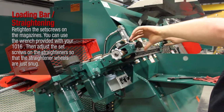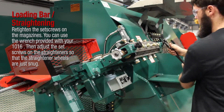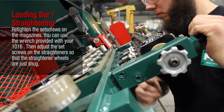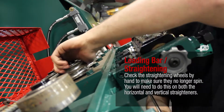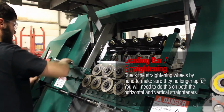Retighten the set screws on the magazines. You can use the wrench provided with your 1016. Then adjust the set screws on the straighteners so that the straightener wheels are just snug. Check the straightening wheels by hand to make sure they no longer spin. You will need to do this on both the horizontal and vertical straighteners.